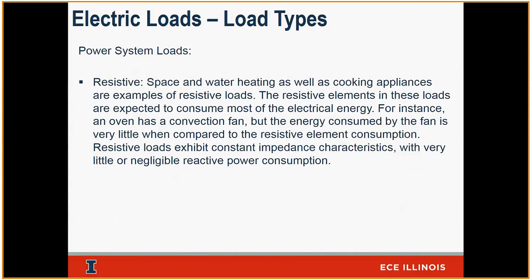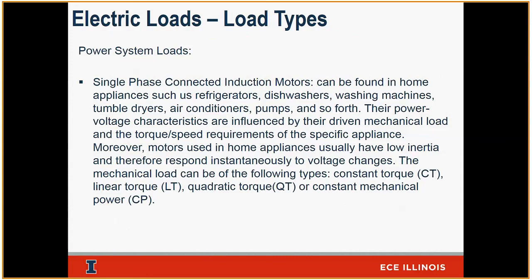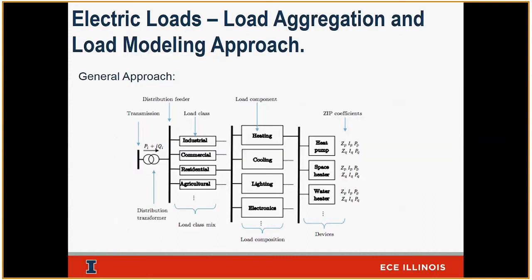I wanted to just cover what a resistive load looks like, what a typical ZIP coefficient for a resistive load looks like, what the lightings look like, what typical large types of load profiles look like, and then how we aggregate them. Remember, we break them down into industrial, commercial, residential, agriculture. These are my classes.